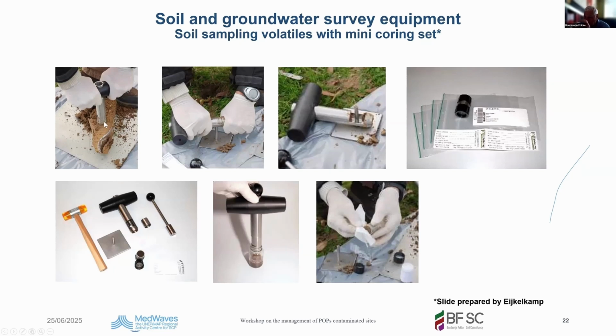You take your auger directly from the borehole, you push this, actually the same system, a ring inside the tip of the auger, because this tip is the most undisturbed part of your auger. You take it off, you put it in your bag. Oh no, this is clean, sorry, this is the sample container being cleaned. Here it's put into the jar, and then the jar is being brought to the lab. This is for manual augering, for sampling volatile components.